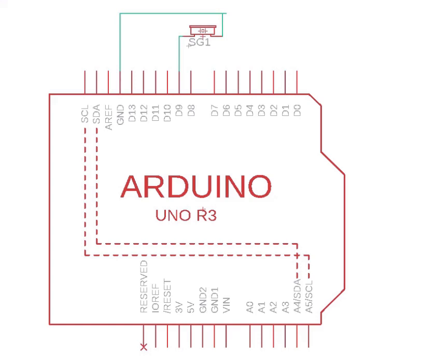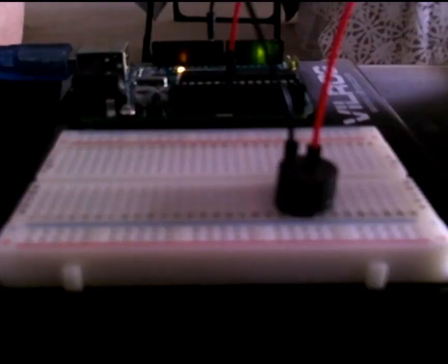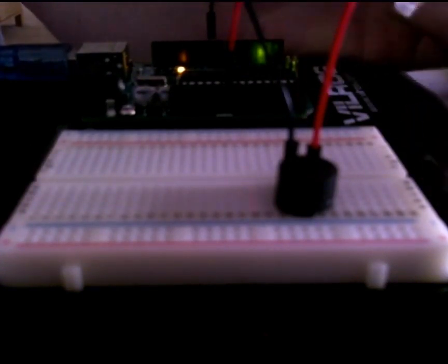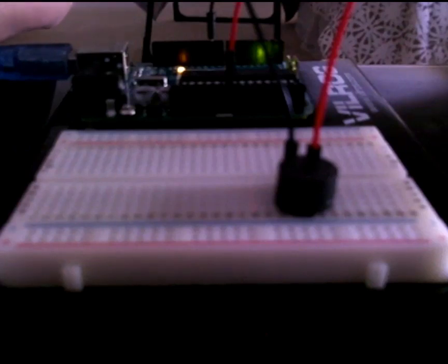back to ground. So if we flip over to the actual circuit, as you can see, we've got our piezo buzzer unit here, and it's connected to a control unit, which is then connected back to ground. The only thing to think about when you're looking at one of these is that your piezo unit is, like LEDs, directional. It's got a positive side and a negative side.